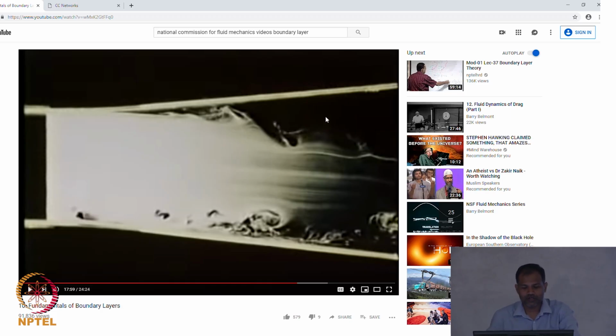All this region is actually occupied by black. That means the fluid is coming in a different way. This black region should be thought of as a region that is separated from the mainstream. If you were to see what is in the black, you would see the flow in the opposite direction, as we saw earlier. While in turbulent flow, the fluid is almost sticking to the wall much further downstream. Therefore, a turbulent boundary layer sticks to the wall much more than a laminar boundary layer.